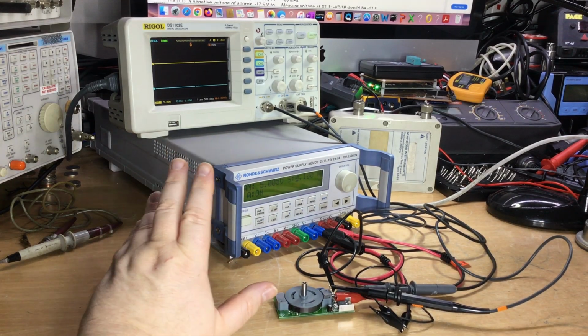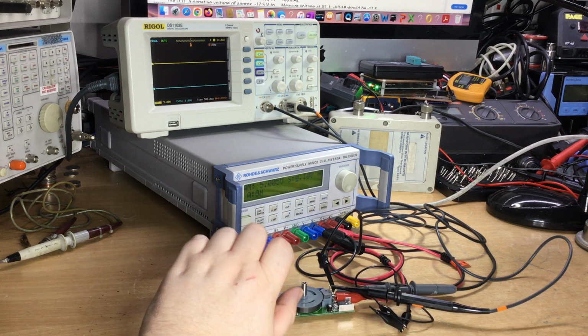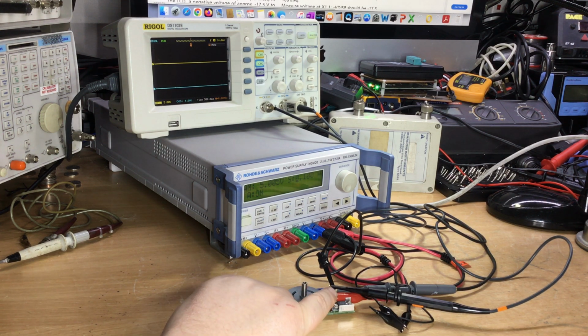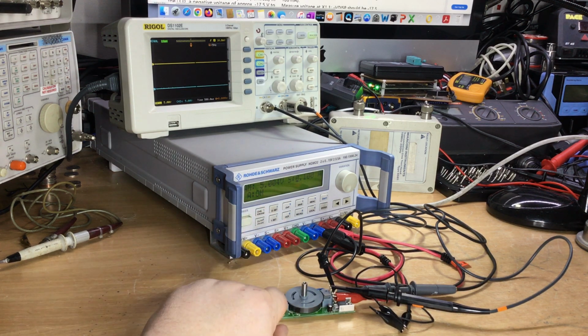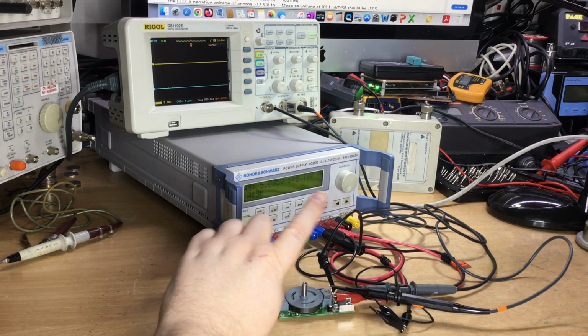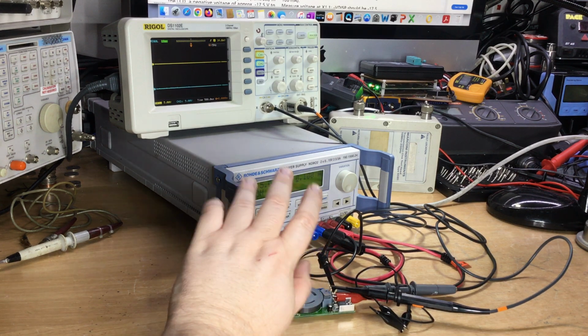Okay, we set up an experiment now where we're going to power this board to do some tests and measurements, and as per the recommendation in the service manual, we've applied 4.7k resistors between the 5 volt supply rail and the Hall effect sensor outputs for both pin 3 and pin 4 on the socket. So I've soldered 2 resistors in there to pull up the lines.